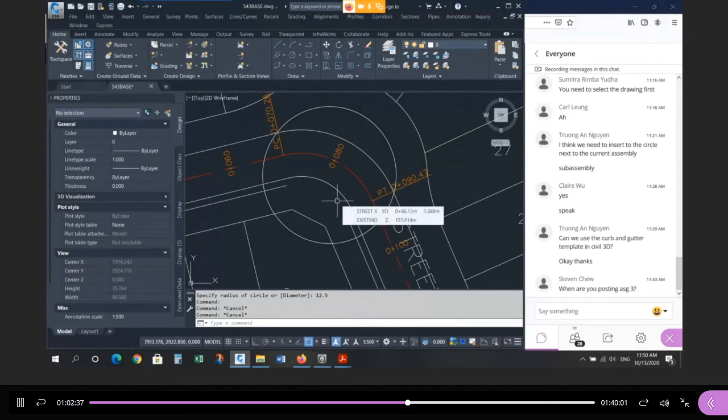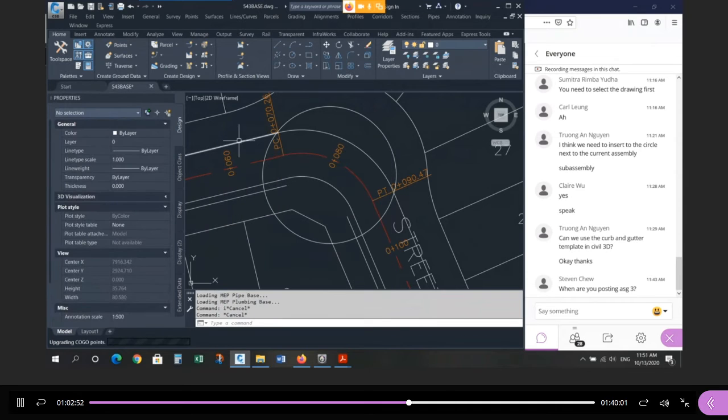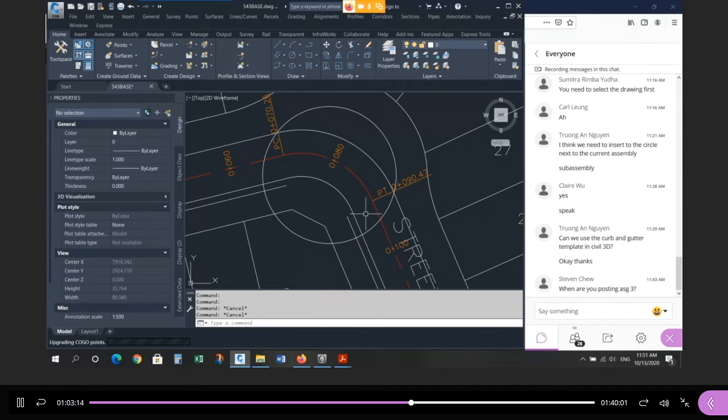Okay, so your O-snaps, you have to really use them properly. If you want to draw a line and click on a spot where the intersection is explicitly shown, then it's a one pick, right? So L, I, and T. If this intersection exists, you can pick it. If you don't want to snap there, if you draw a line, INT, you can go off the line and it gives you that dot, dot, dot, and then you get to pick two things. I want the intersection of this thing with this thing, and it solves it for you. So you don't have to necessarily fillet these two together. Okay, so that's how I do it. It's up to you. Again, these are just little tips and tricks along the way.